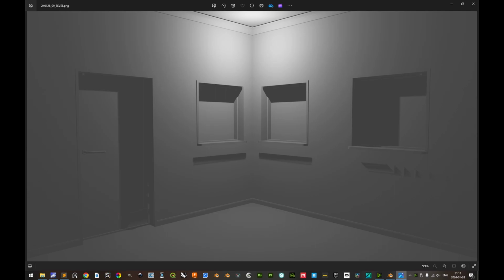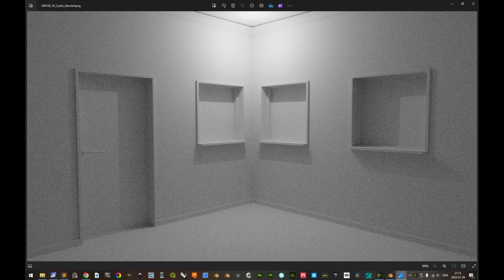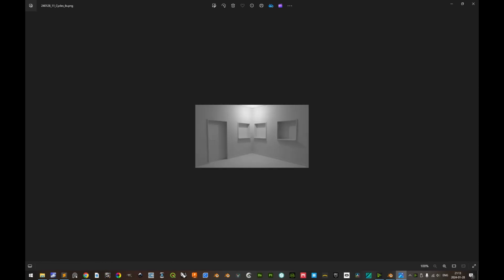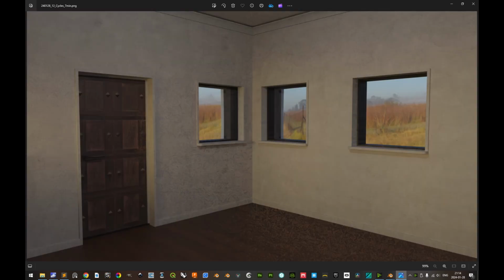Alright, so let's see here. First we started with an EEVEE render, real time. And then we switched to the Cycles render engine. And then we used 25% scaling in the resolution, and also with the much higher noise threshold, so as to be able to iteratively work with Cycles render. And then for this first try, for the final image, the denoising pass produced an abhorrent image. So we switched back the noise threshold for the final render to 0.01. This produced after 1 hour and 14 minutes this image before the denoising and this image after the denoising.